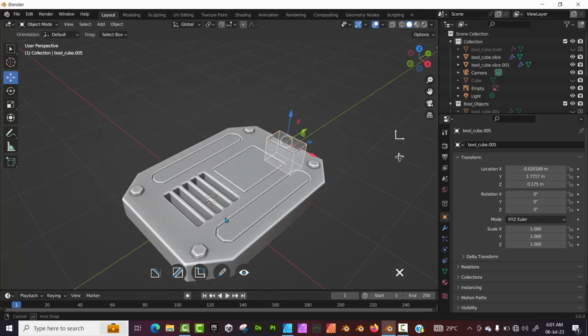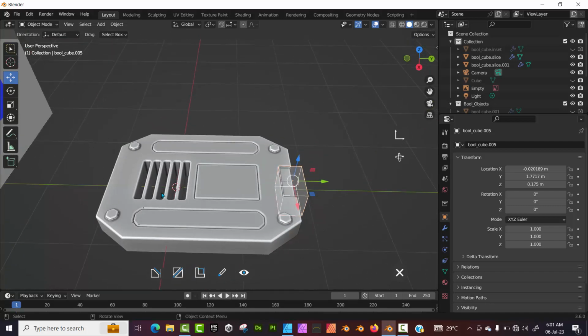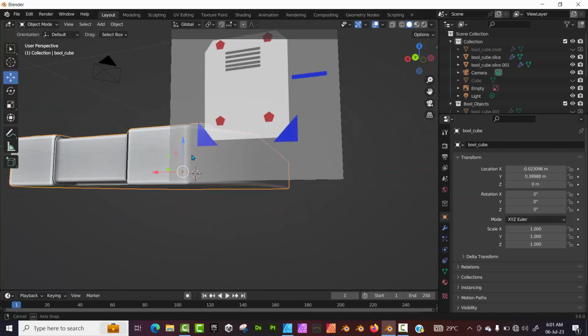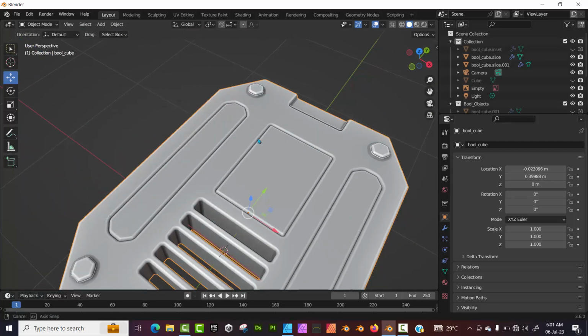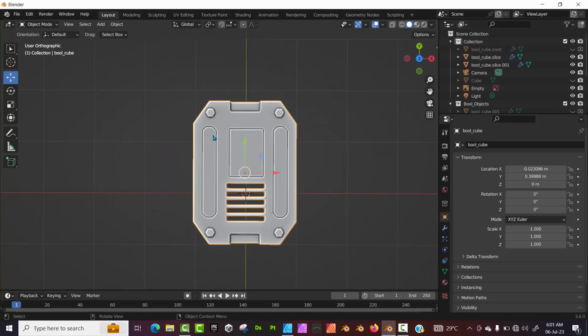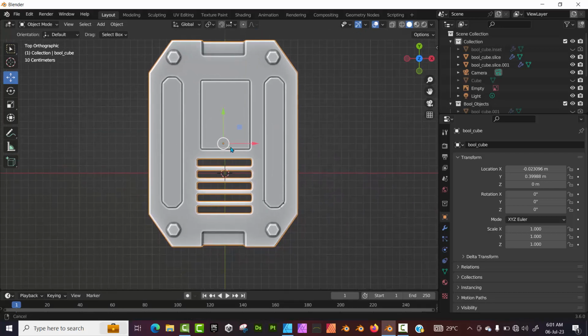and let's see how it looks. Let's mirror it along the y-axis. So let's right click, go to mirror, and then mirror it down here. Right click and say validate, and let's right click anywhere, and you can actually see what the inset does. That's a nice cool looking inset on our object. So I'll just stop here so I don't overdo this.